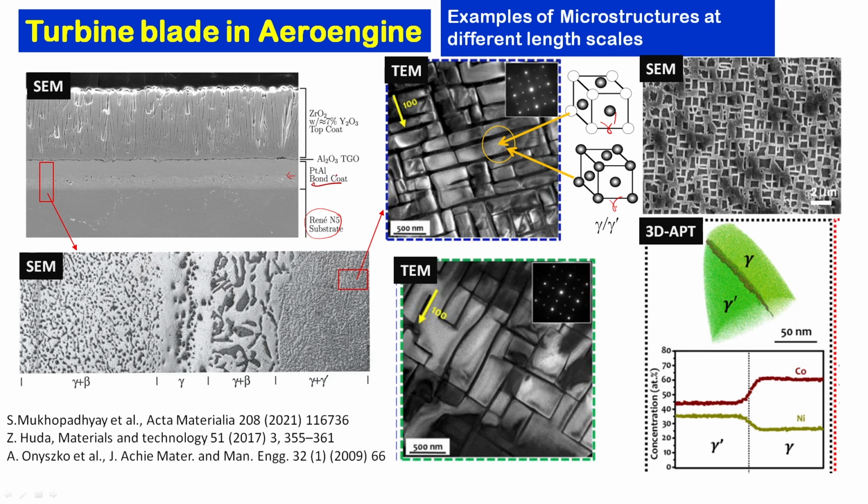This is a technology in itself, that is not a very small thing to understand. You can see the length scale also. So the top coat is not very thin, it should be hundreds of microns, and the bond coat will be thin, about 10 to 20 microns, and then the superalloy blade has a certain specific structure. If you look at the superalloy microstructure, this has a gamma prime microstructure.